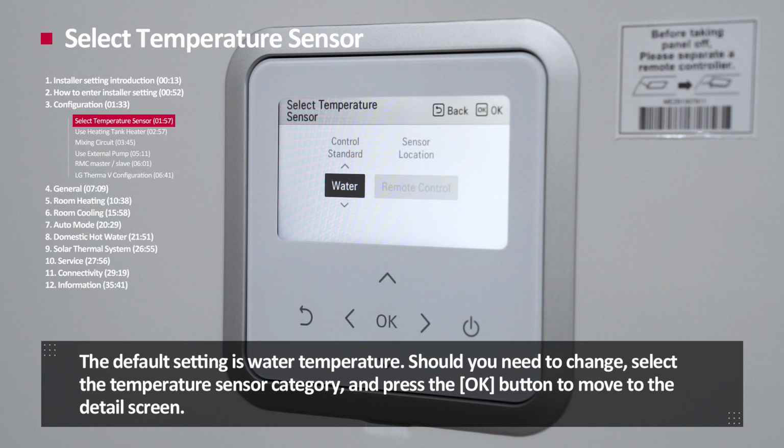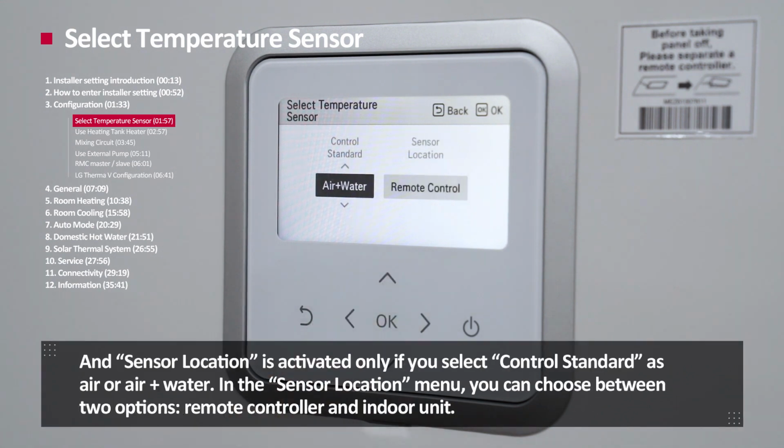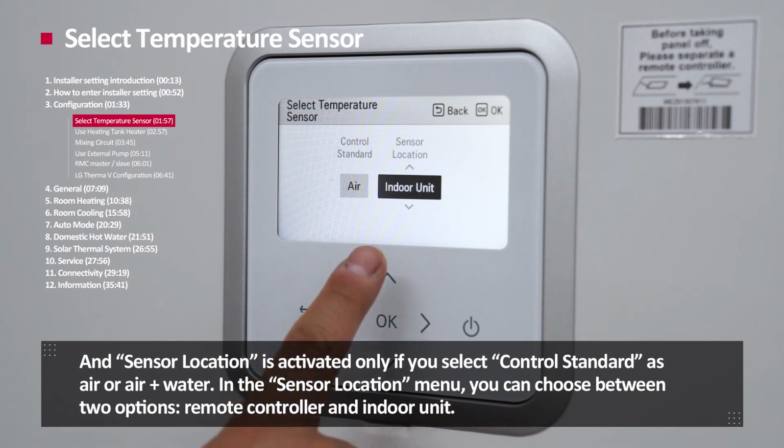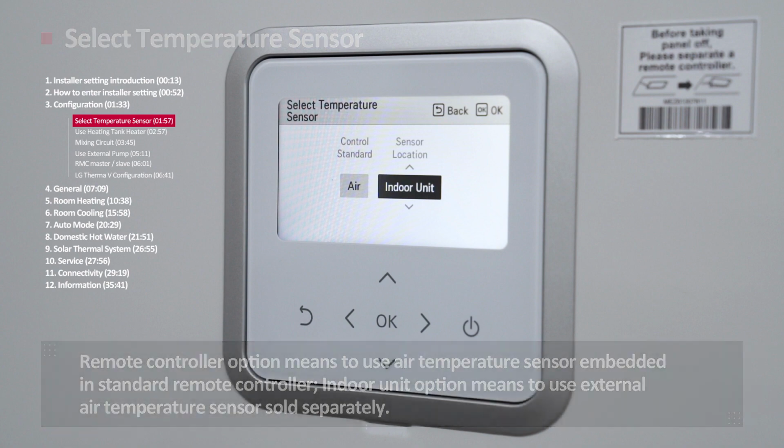Should you need to change, select the temperature sensor category and press the OK button to move to the details screen. There are 3 options under Control Standard category: water, air, and air plus water. And sensor location is activated only if you select Control Standard as air or air plus water. In the sensor location menu, you can choose between 2 options: remote controller and indoor unit. Remote controller option means to use air temperature sensor embedded in the standard remote controller. Indoor unit option means to use external air temperature sensor sold separately.